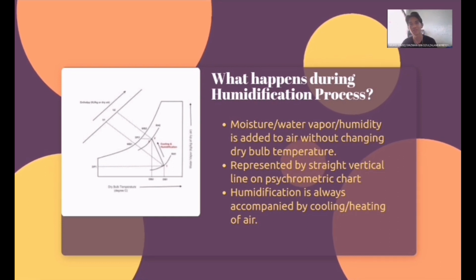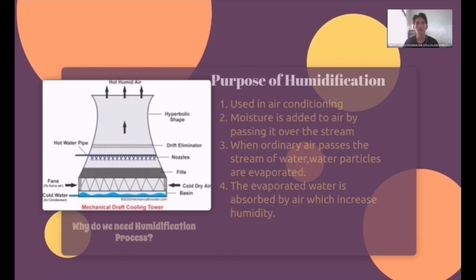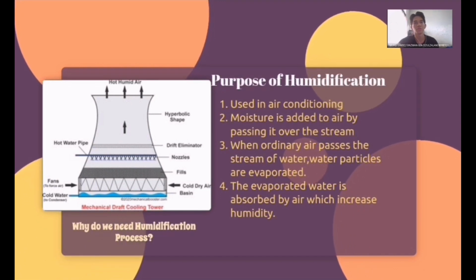In actual practice, pure humidification is not possible since it is always accompanied by cooling or heating of air. Humidification process along with cooling or heating is used in a number of air conditioning appliances. So why do we need the humidification process? Cooling and humidification process is one of the most used air conditioning applications for cooling purposes.